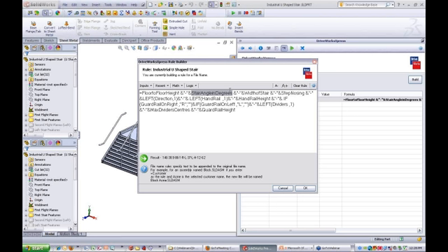Now the default way the file name is created in DriveWorks Express is to append this rule to the original master file name. That's why we had that long name before, industrial U-shaped stair 200-42- etc., etc. So we can add simple information such as data entered into the form, or things like this using the left statement.